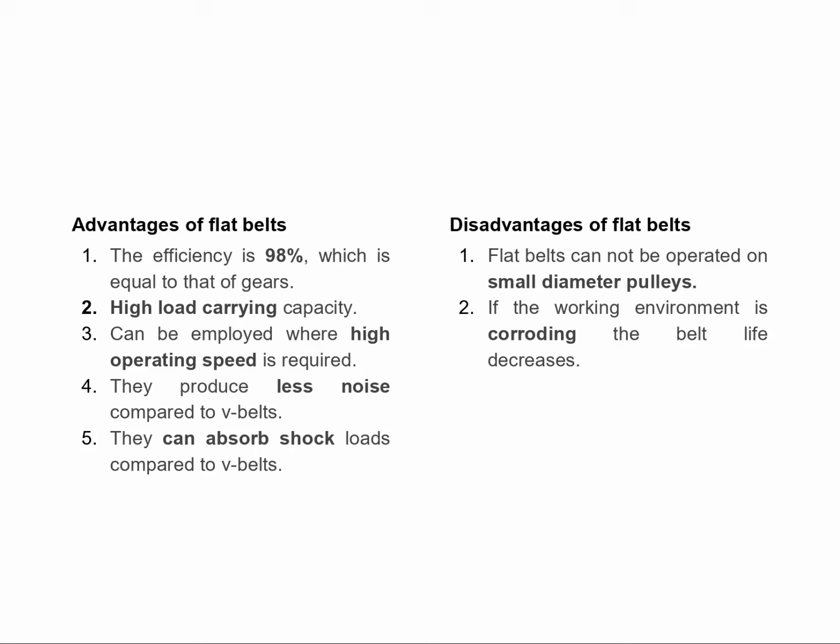First, let us take advantages of flat belts. The efficiency is 98%, which is equal to that of gears. Second point, high load carrying capacity. Third point, can be employed where high operating speed is required. Fourth point, they produce less noise compared to V belts. Fifth point, they can absorb shock loads compared to V belts.